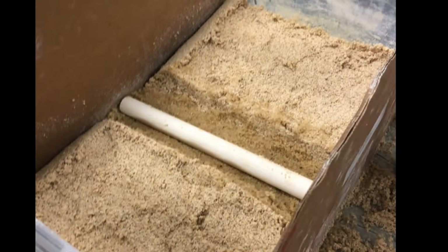The surrounding soil is needed to create stability of the system, and metal culverts will deform under their own weight without lateral support from the soil. More design considerations include the suitability of excavated soil for reuse as backfill, which reduces environmental impacts since you're essentially recycling excavated material.